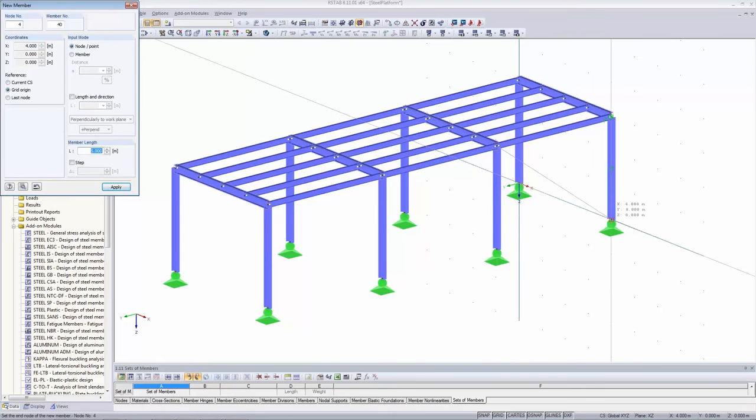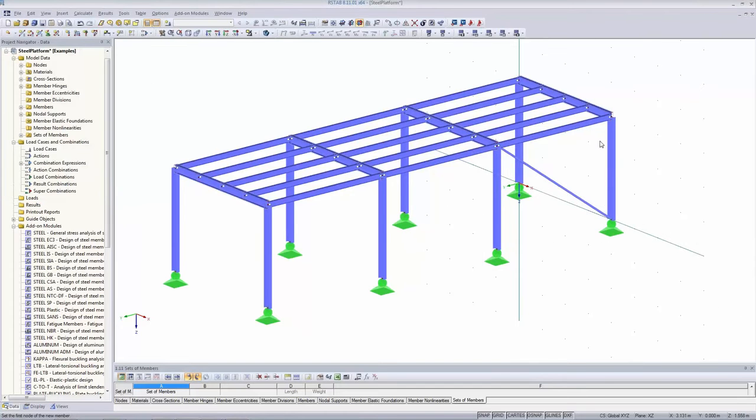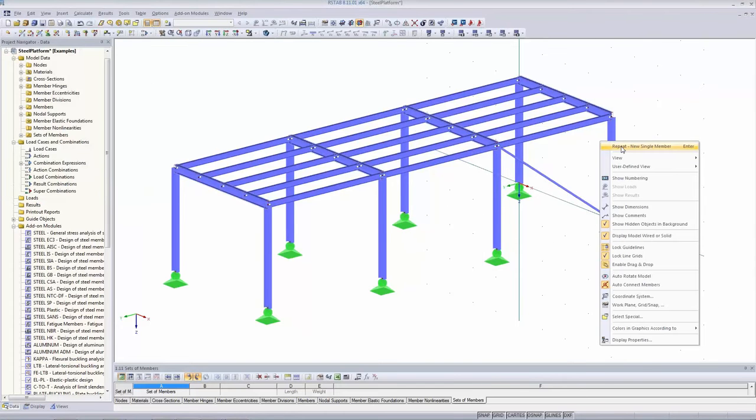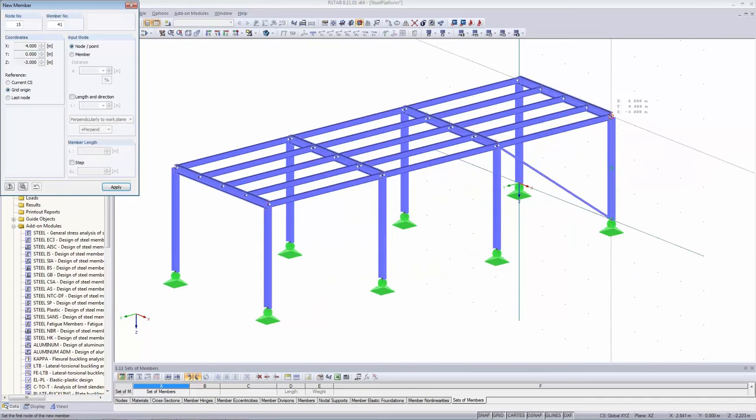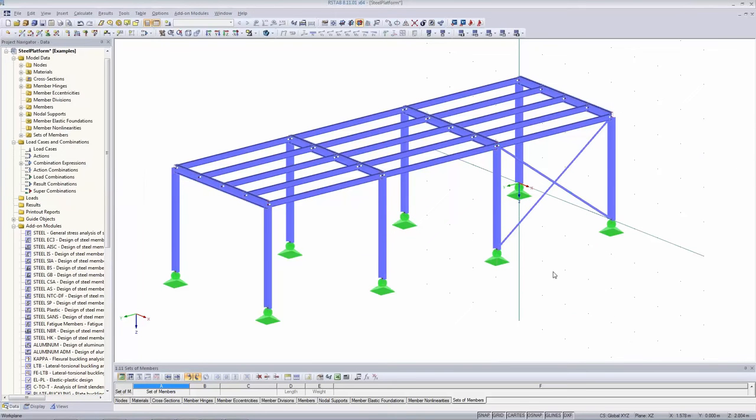click here and there. This is my first member of the brace, and repeat single member. So when you right click, you stop some things you do, and when you right click again, you can open a context menu and you can repeat the previously done. So it's the same member, so here and here. And I click right because I finished defining members.